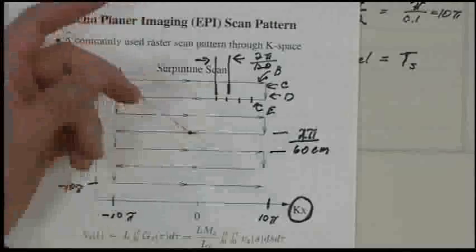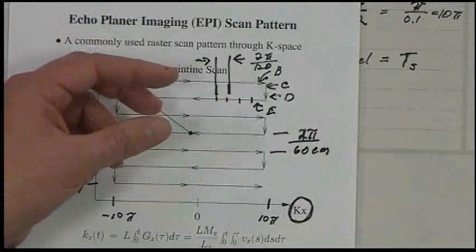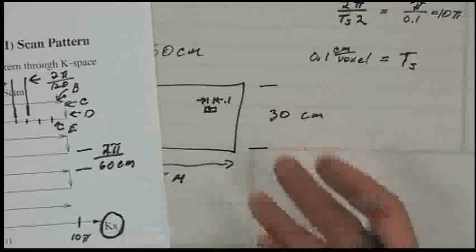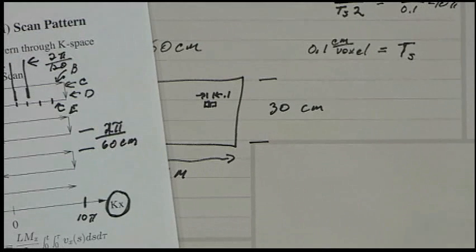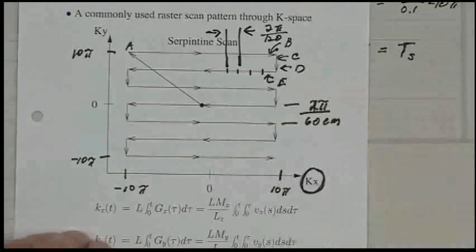Of course, when you really do this, you have to be a little bit conservative. You tend to sample at a slightly higher rate than the minimum necessary to make sure you don't have any problems. And maybe you don't know precisely how big the person is, so you oversample a little bit to make sure you don't have any problems. And even if you oversample, it's not the worst thing, because you get a little better signal to noise ratio if you oversample a little bit. All right.